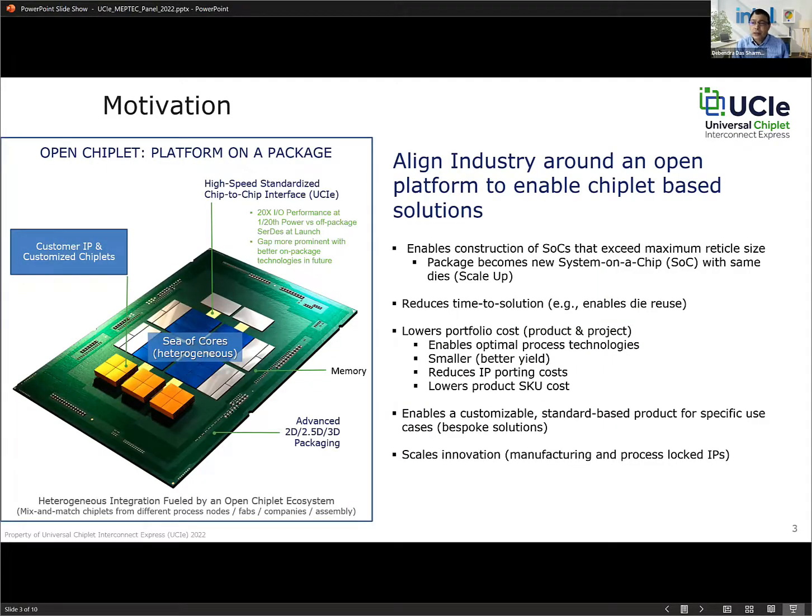We talked about earlier today there are two considerations primarily why a lot of people are doing chiplets, and most of them are proprietary. We are up against the reticle limit, and the other one is the yield consideration. So fundamentally these are things that are functionality that are similar. For example, you can create a larger number of core dies by having small chiplets with a lesser number of cores, and then stitch them together at a package level. That is what I would call a scale up usage model primarily. And there are other benefits, which is what we would call the heterogeneous integration of the chiplets.